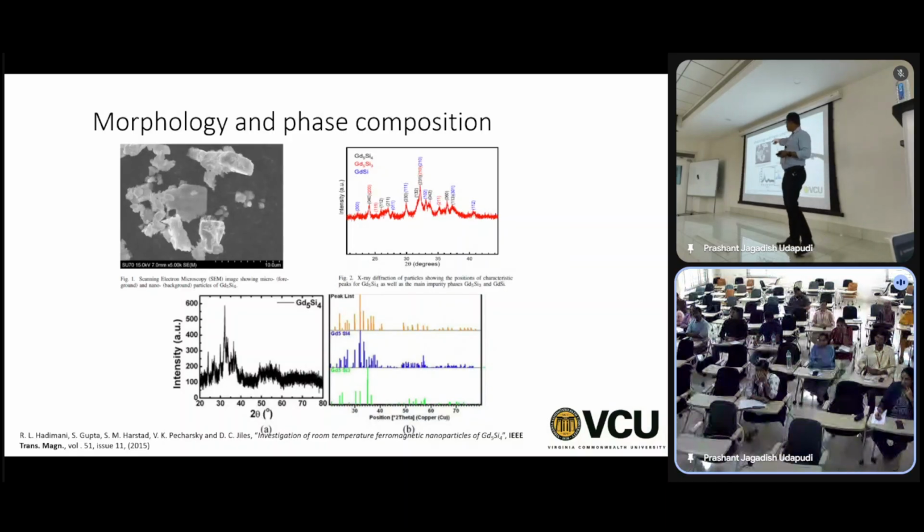Okay, so that means when we did ball milling, we changed the chemistry a little bit, and we got some impure phase, right? So this is how you characterize the powder, so that when you use it in additive manufacturing, you get the material you want. Okay, and again, here are the reference peaks of different phases. When you don't clean the signal, this is how it looks. And when you remove the noise, you get a slightly better signal.